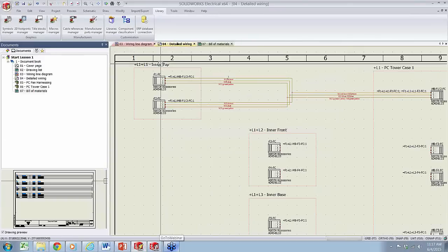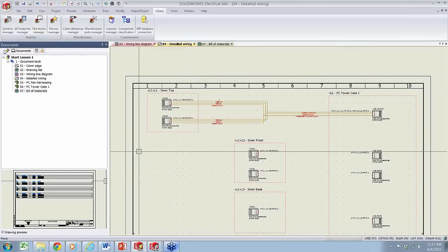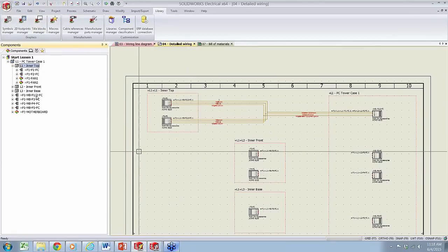So back in my electrical schematic, I can insert the part the traditional way: we build the symbol, then we insert the part. Or we can do it as a kit, where I add the component to my tree and then insert them later. Or let the mechanical engineer add them through the components tree, because we both share the same component navigation.